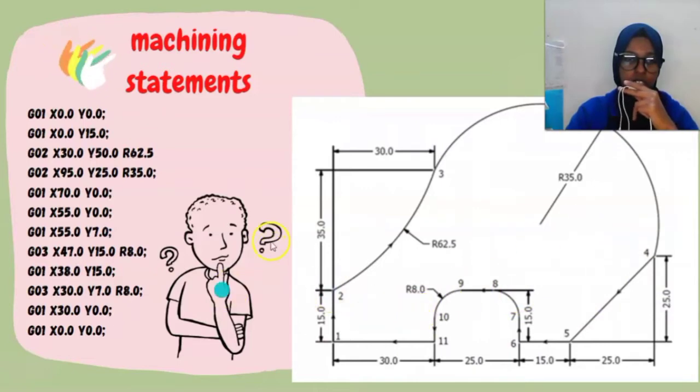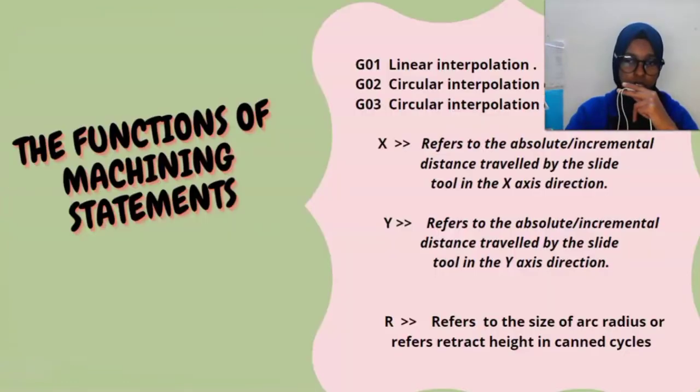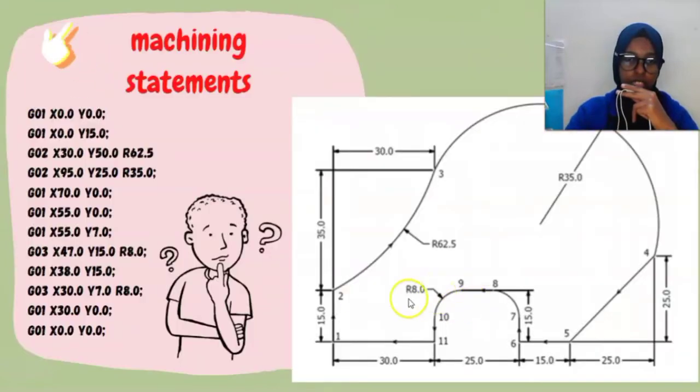And G codes, actually these G codes tell the machine to perform certain functions, and the G codes are modal, which means they remain in effect until replaced by another modal G code. And if it's rotating this way, it's G02, which means it's a clockwise direction, and this way counterclockwise it's G03.